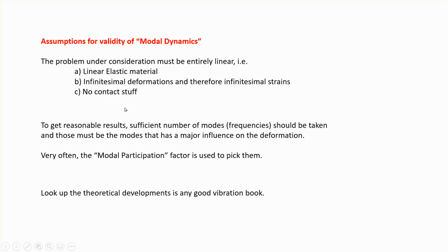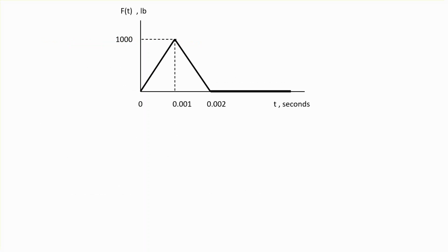Now, it's a good idea if one has a feeling for the theoretical development behind this method or any method that is being done with finite elements, and I suggest that you look at a respectable vibrations book. Now, here's the situation. The loading that we apply is going to be like that. It's not quite an impulse load, but you can think about it as something close to it. So the load starts from 0, goes up to 1,000 pounds, and then drops within this time frame. And of course, that will lead into dynamic analysis.